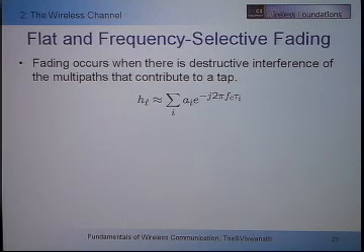And now we want to think about two types of channel. One is called a flat fading channel, and the other is called a frequency selective fading channel. What does a flat fading channel mean? Flat means that the frequency response is flat. Frequency response being flat is equivalent to saying that the impulse response is what? All right, I've got to get people thinking now. Sorry? A delta, right? The discrete time filter should be a delta. A delta means one tap, essentially.